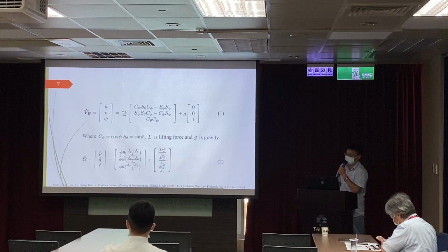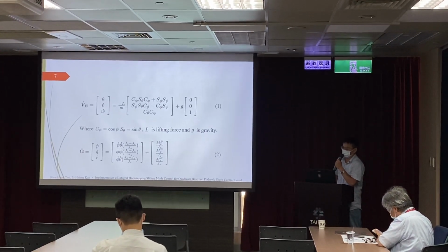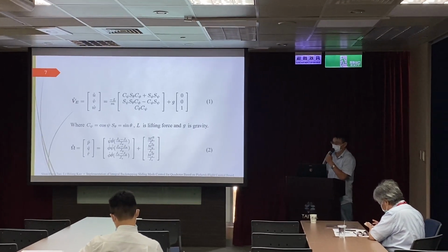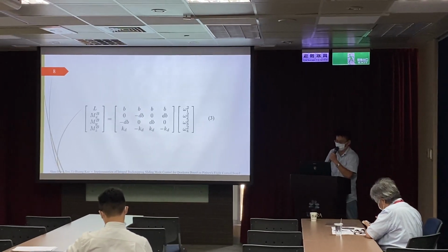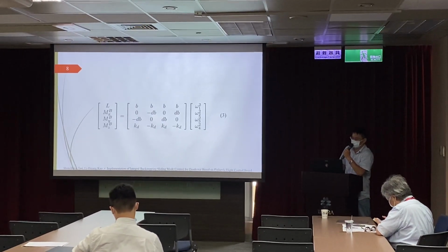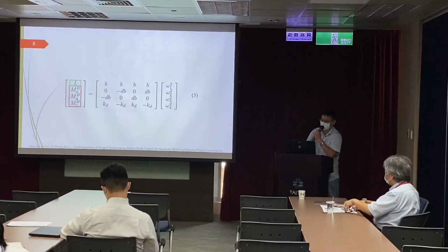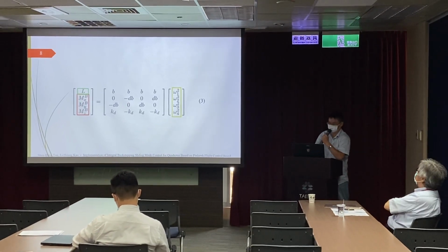By utilizing Newton's formula and aerodynamic relations, we can obtain the translational and the attitude dynamics presented in equation 1 and 2. The relationship between the rotating torque, lifting force, and the motor angular speed is shown in equation 3.